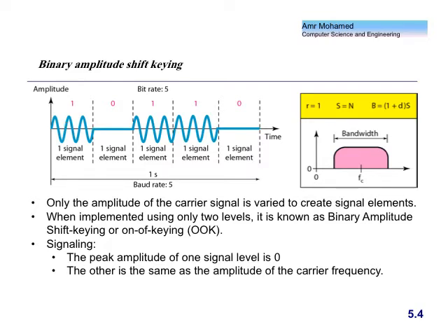So this means that now I have a bandpass signal. It's no longer a low-pass signal where I have some zero frequency component. I shifted the signal in the frequency domain. So the signal will now be shifted in the frequency domain around the carrier frequency, and this carrier frequency is the frequency of this sine wave. Right? Okay?